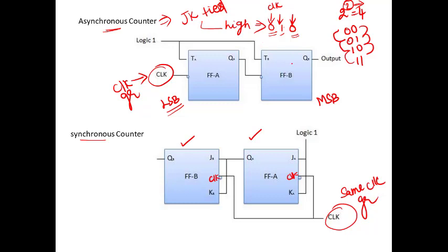Okay. So, for a synchronous counter, I may use any flip-flop for designing because all the clocks are synchronized with respect to the same clock generator. So, whatever input that I am giving according to the design, you will get the output. This is the basic difference between your synchronous and the asynchronous counter. We have only one clock generator. In case of an asynchronous counter, in subsequent flip-flops, the output of the previous flip-flop will be fed to the subsequent flip-flops as the clock, so you will be having a delay in the output of the second flip-flop here.